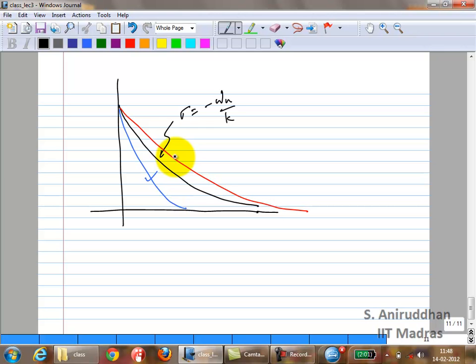If you plot your settling time versus damping factor, what does it look like? What is that eta equal to 1 called? It's your critical damping, right? This thing is similar to that, where you had a critical amount of delay. You can actually settle faster than a case where you have a single pole.